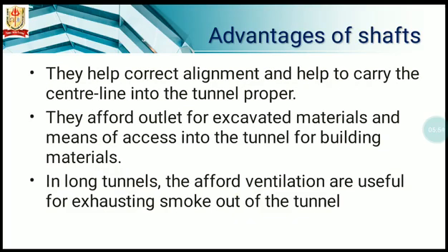Advantages of shafts: they help to correct alignment and help to carry the center line into the tunnel proper. They afford the outlet for the excavated materials and means of access into the tunnel for building material. In long tunnels, they afford ventilation and are useful for exiting smoke out of the tunnel.